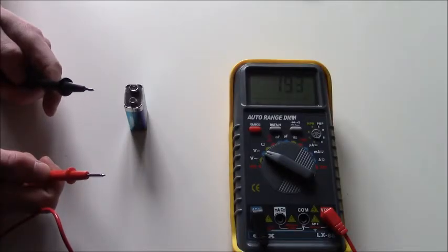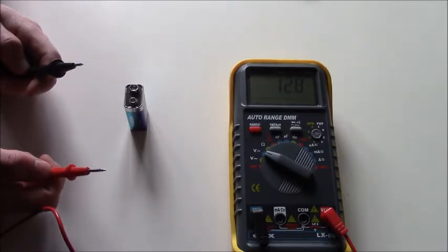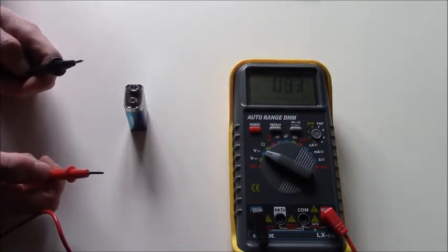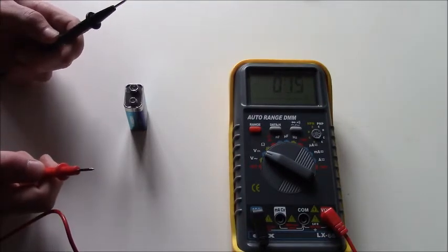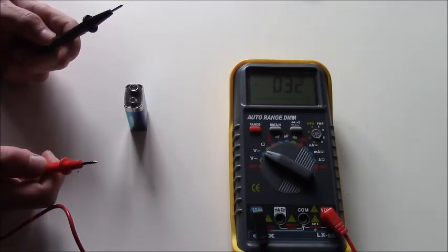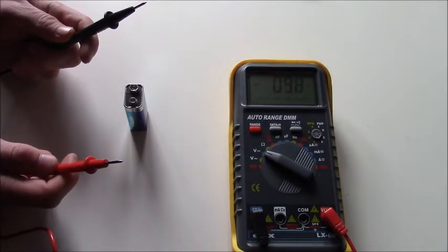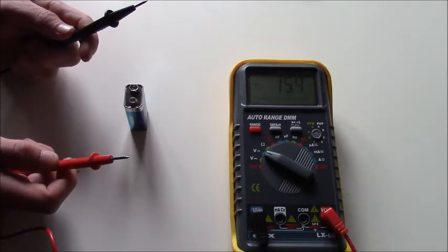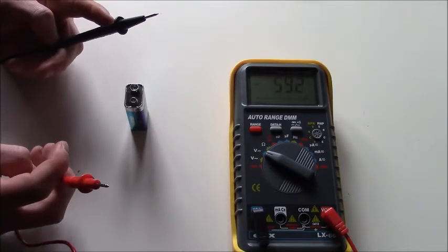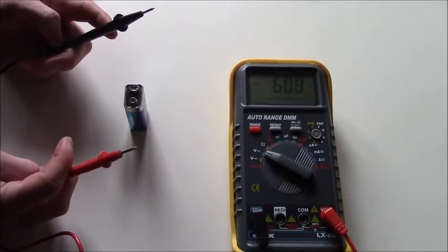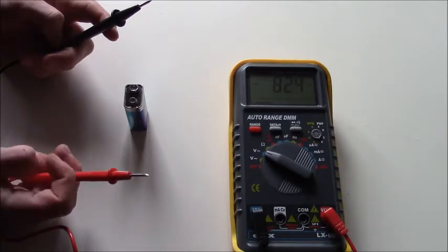If you want to measure one of the basic units of electricity on a cable or a power source, you can use a multimeter. A multimeter can measure these units in a safe way. The multimeter has two pins, the positive and the negative. The positive is the red one and the negative is the black one. If you want to measure the voltage of a source, the position of the pins does not really matter. This means that you can switch the positive and the negative and still get the right measurement. When you turn around the two pins, you get a negative reading, but it's the same as the positive reading.